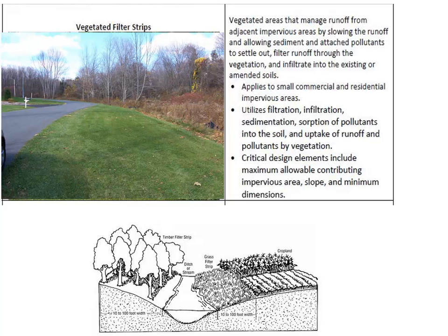And so one of the things that you can do is put in vegetated filter strips. If you just think about the runoff coming from a roadway, if the runoff has to flow over a vegetated area before it gets into a drainage canal, here this is, I think, a sloped canal at the edge of that vegetated filter strip. So if it's forced to flow over grass before it does that, it's going to infiltrate into the soil.